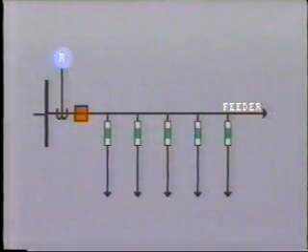On most feeders, there are a large number of fused taps supplying different customers. The protection scheme may be coordinated so that if a temporary fault occurs downstream of any fuse, the feeder breaker protection will operate first. It will instantaneously trip the breaker and then instantaneously reclose again.